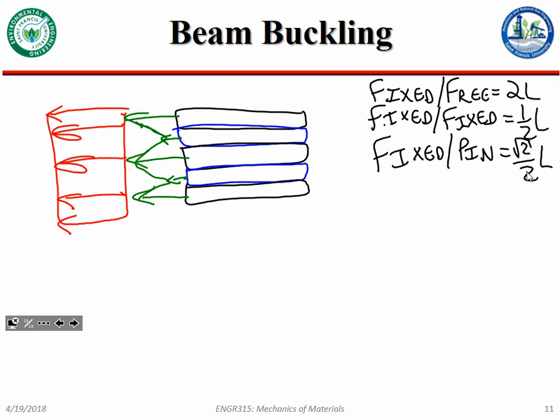So while it could fail in buckling, there's a significant chance that it's actually going to delaminate first, that each of the reinforcement layers of the glass is actually going to peel off of each other before the whole panel fails. So it's actually a really interesting question that's really hard to answer.